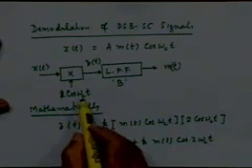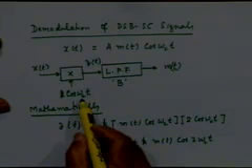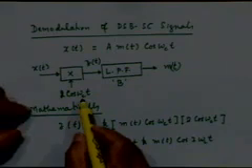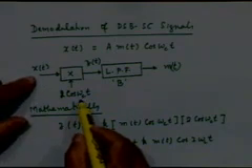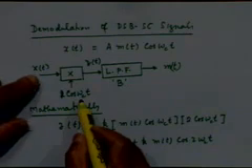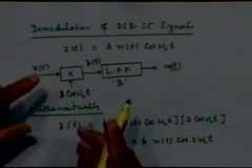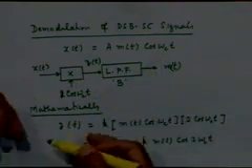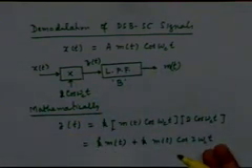This local carrier must be precisely at the same frequency as the one that you use at the transmitter. It should have precisely the same phase as the phase of the incoming signal carrying the incoming signal. Because if these two conditions are violated, you will not get a perfect demodulation of the kind that we have proved mathematically to be so.